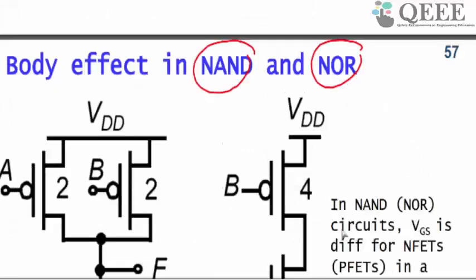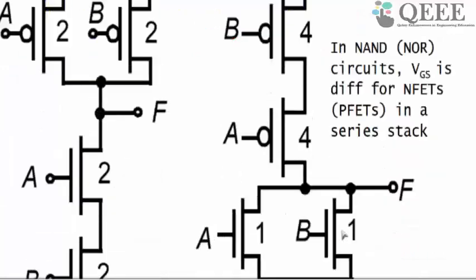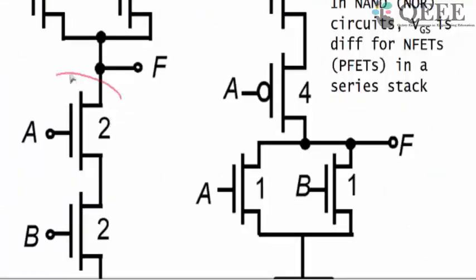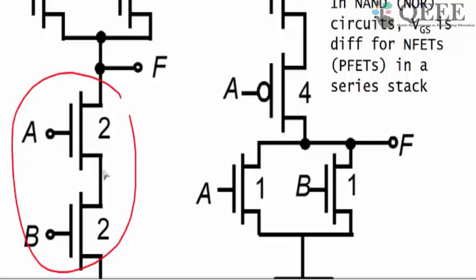It is an extension of your CMOS NOT gate, but the NOT gate has only one input, whereas the NAND gate has more than one input. In the NAND gate, there are two NMOS transistors in series. These are known as the pull down configuration.